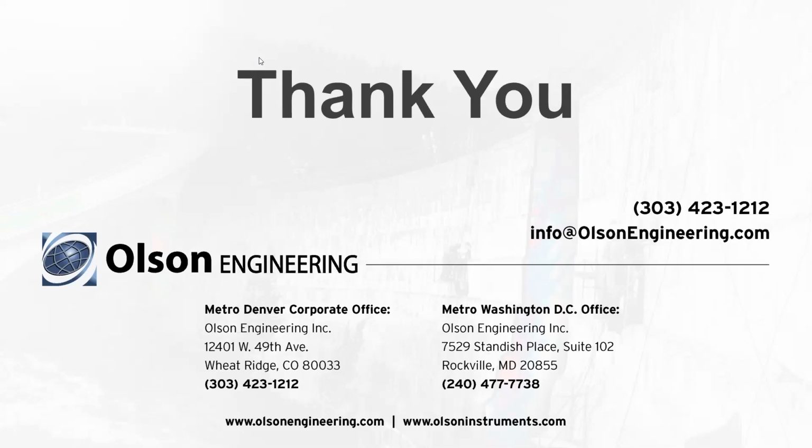All right, so the next question says, what is the accuracy of impact echo testing on a wall on the seaside? On the seaside, meaning an ocean? I assume that means on the wet side of a dam structure if you use maybe the submersible IE sensor. We have had divers go down on bridge piers underwater and check the extent of cracking damage due to ship impacts to the bridge piers. And it worked quite well. You will see in about up to 6 feet. It's very well coupled because of the water.